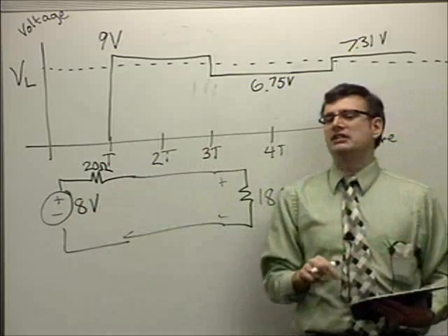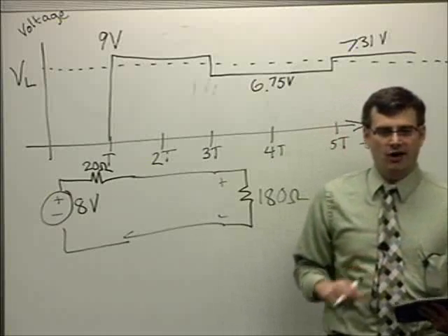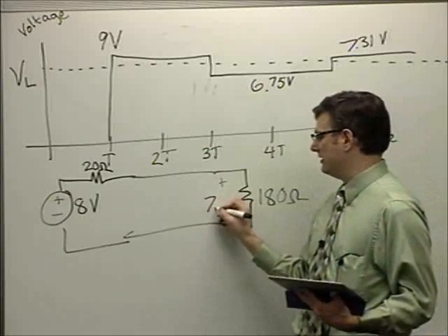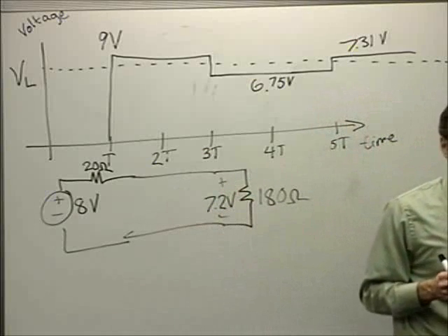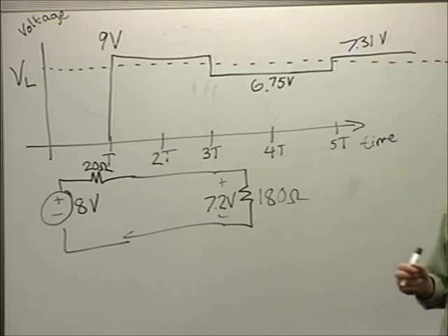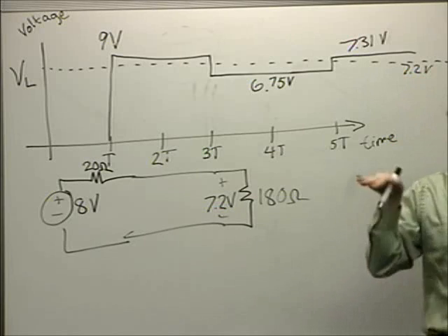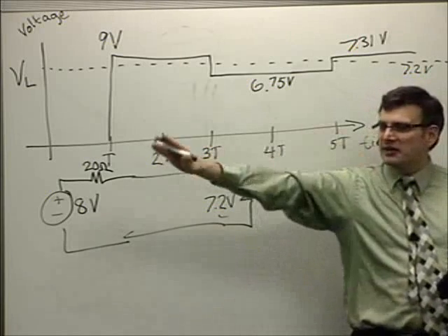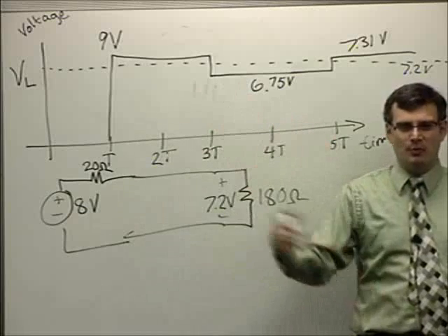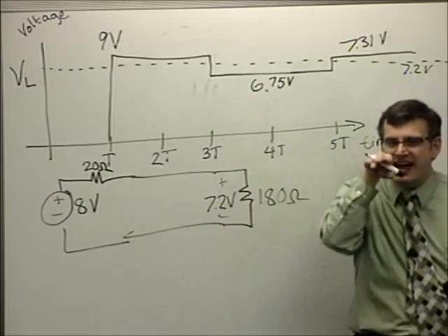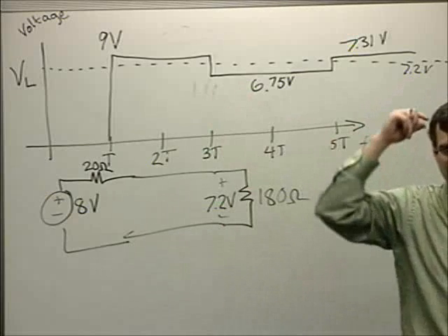We work that through the Magic Professor calculator, where everything is calculated ahead of time. Oh, that would be 7.2 volts. 180 divided by 200 times 8. 7.2 volts. Lo and behold, that looks exactly like the value that we're converging to. Remember, in the transient, it's going to take an infinite amount of time to shake itself out, but after maybe 20 or 30 transit times, you won't be able to measure the difference. And you're asymptotically jumping up and down around that 7.2 volt DC waveform.